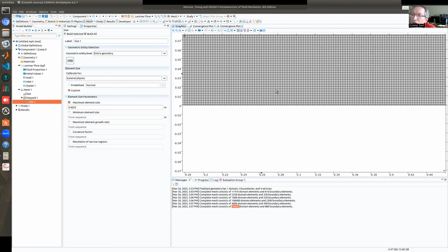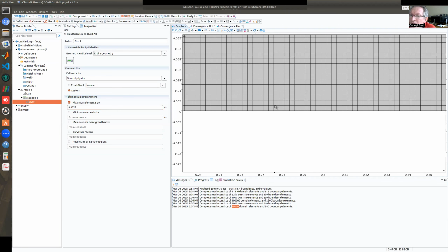So over each of these elements, maybe at the corners of these elements, also maybe at the centers of the edges and maybe at the midpoint of the elements, we will calculate velocity components and pressures. So in this solution, there will be more than 10,000 velocity values, U and V velocities, and more than 10,000 pressure values. Over each element, there will be UV velocity and pressure.